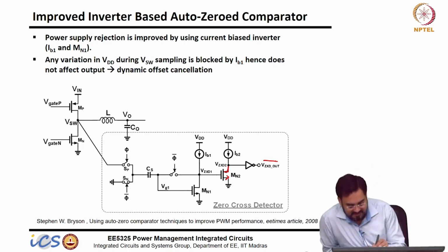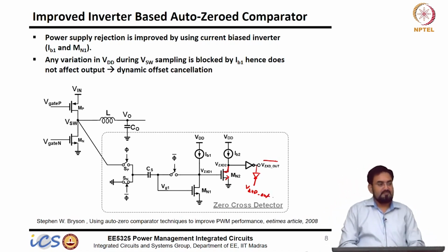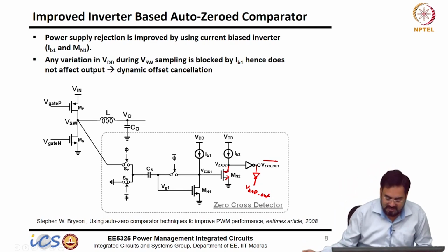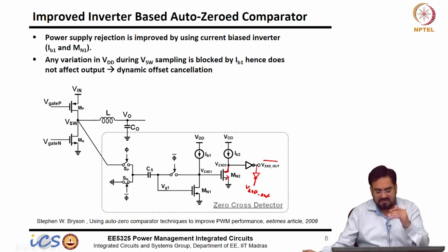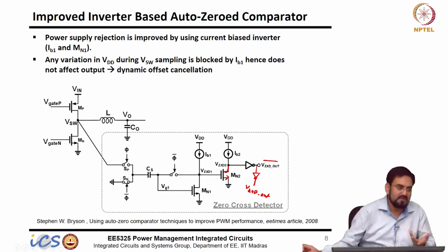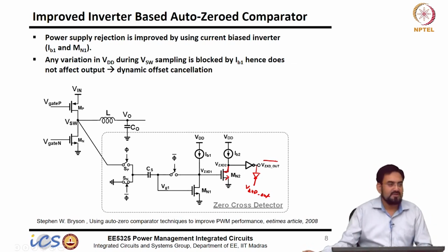So which means if I have one more inverter, then I will get, okay. So the reason I am having this one more stage, I could have used an inverter directly at the output, but in order to match the threshold, I am putting it here, so that you basically trip this at the threshold, and then again apply these two inverters to get rail to rail output. Okay.